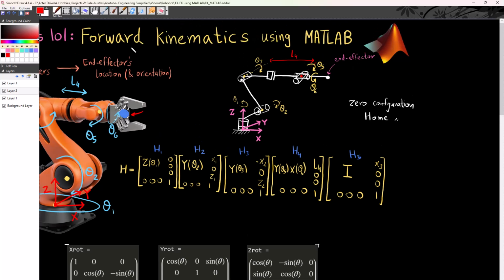So what I did in this was I wrote out the homogeneous transforms h1 through h5 and I multiplied them out, and what I got was a forward kinematic, this one, fk, which I called fk in my code, or I can just simply write as h. And what I am going to get is a homogeneous transform of the normal form. So it is going to have 3 zeros and a 1 at the end.